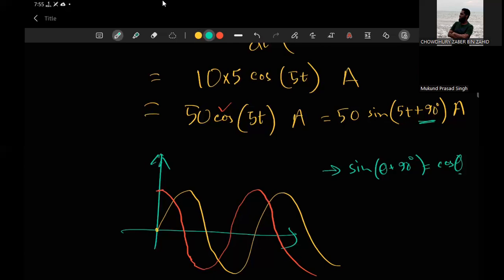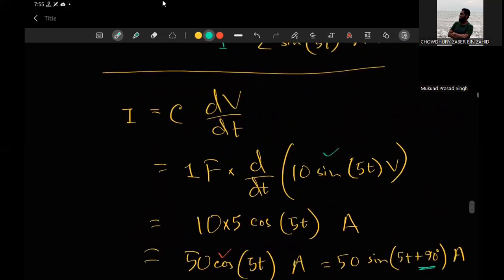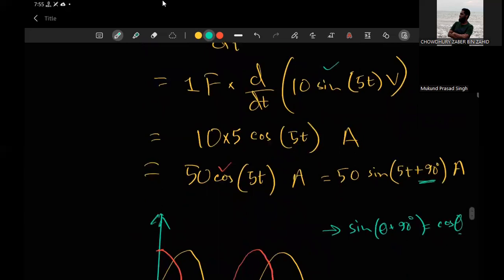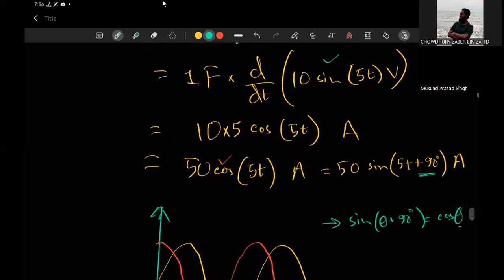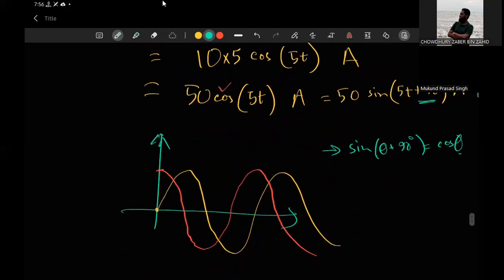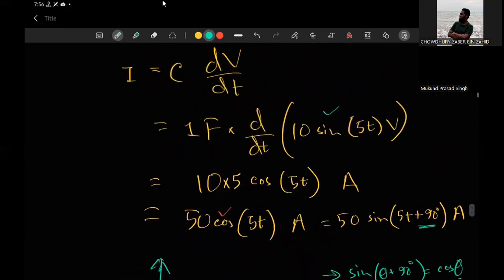And so this is why basically it acts almost like a resistor, except for the fact that we need to change the sine into cos somehow, right? We must remember the 90-degree angle here. So there is a way to do this. Basically the job of engineers is to simplify things. Instead of working with sine and cos, if we did this problem in complex numbers, this would become much easier. Oftentimes in math, you will see that if you go to the higher plane, the problem actually becomes easier.